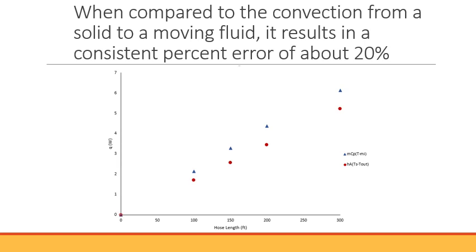With that being said, being able to measure the inner surface temperature of the insulation and including the insulation itself in the analysis may yield better results. Additional analysis regarding these carpet cleaning hoses would be to see how different surfaces that it lays on affect the heat transfer and exit temperature. For instance, if the 100-foot of hose is laying on concrete versus grass, or dry carpet versus wet carpet.